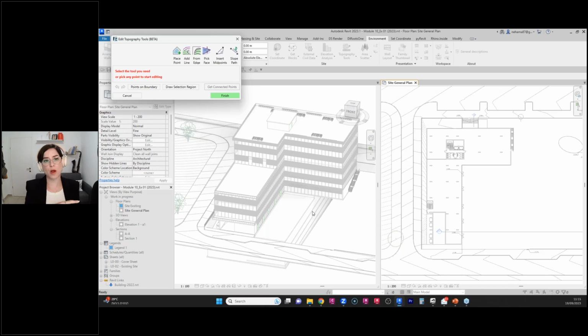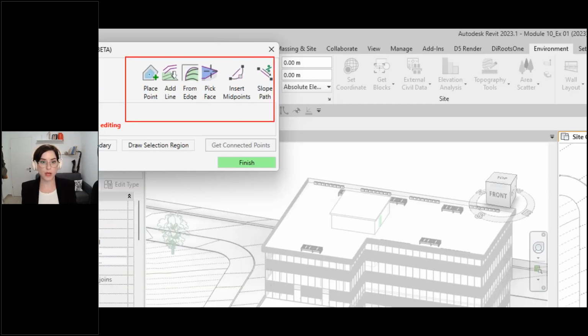Now, if you're moving from AutoCAD, you just have to remember that topographies in Revit can show you the contour lines, but they're actually made out of points. And now the question is, how do I place all these points without having to calculate each and every point? Well, instead of calculating each point, what we offer is 6 sets of strategies that you see here.